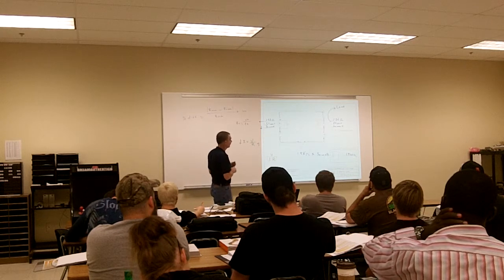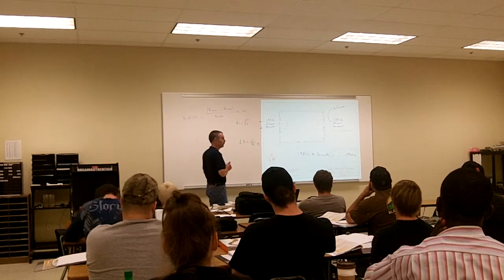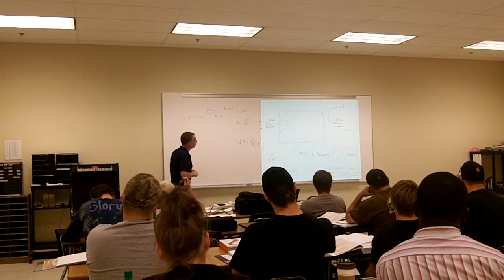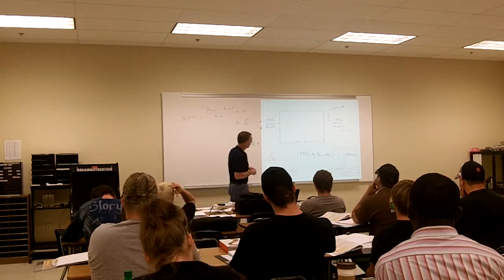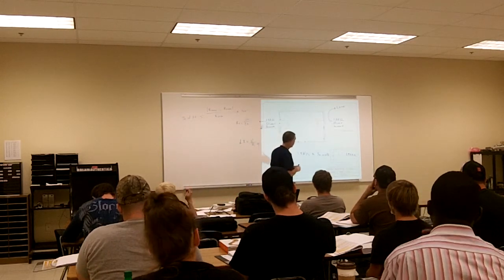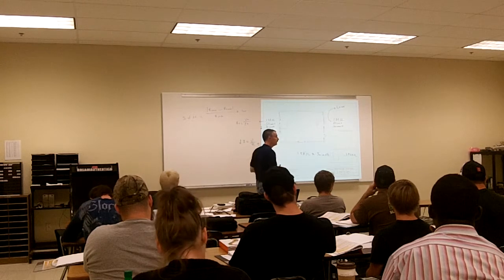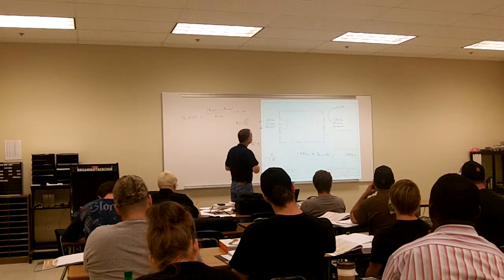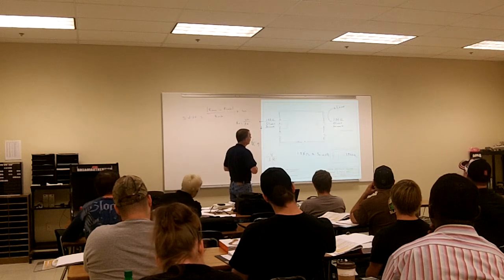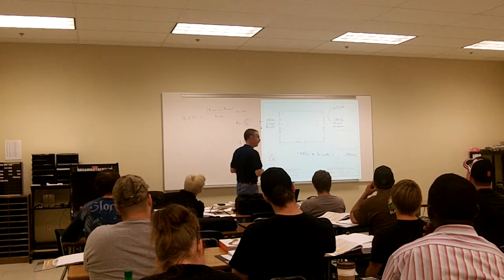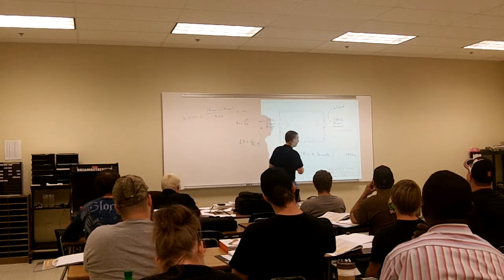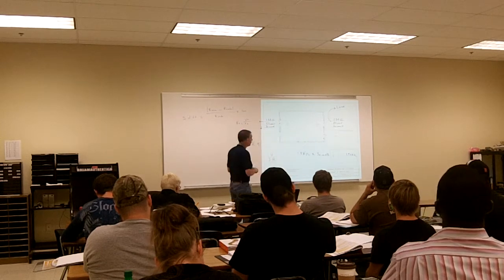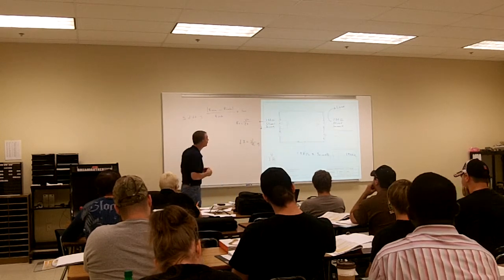How do you figure it out? That would be about 130 ohms extra. 5% would be 90. Yeah, so it would be out of tolerance. I like that, good approximations there. So we couldn't throw that one in there.